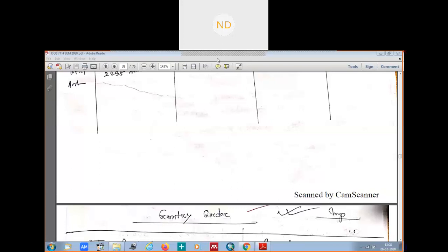Okay. So we were on this thing, no? We have talked about the maximum wheel load, where should be our maximum wheel load, and obviously when you know the position of the maximum wheel load, you can calculate the reactions and find out the maximum load on the crane system. Now once you know the maximum load which is acting, you can find out the maximum shear force.